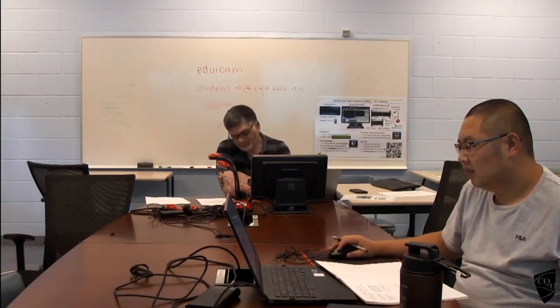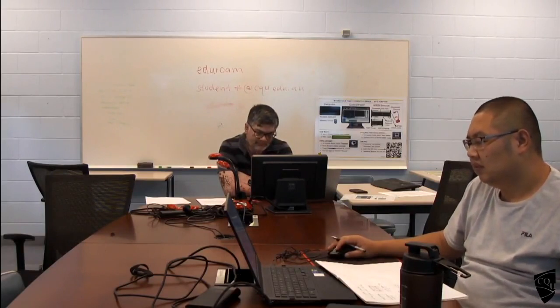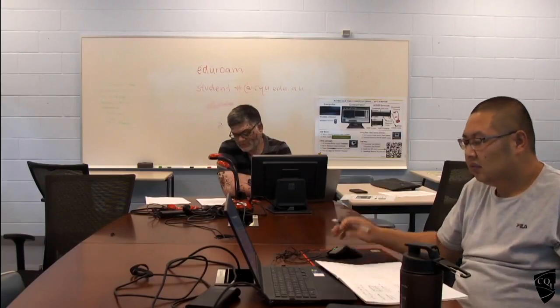Okay, so at the moment I don't have the steel details because that's what we are going to design, or that's what we are going to determine. So in that case, when you start, you use 25 kilonewton per cubic meter.